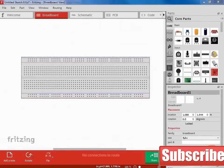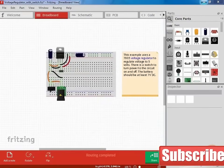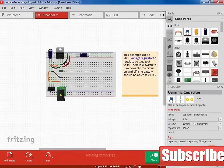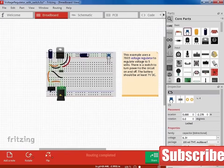This is what the environment of Fritzing looks like. When we open it up, it shows us a blank sketch. Circuit boards in Fritzing are called sketches. Let's load up one of the preloaded sketches. This is a sketch of a simple 5-volt regulator from the 7800 series. Fritzing has this neat little window where we can see it all assembled on a breadboard. We can move the parts around, place them, select new parts, and build our breadboard here.